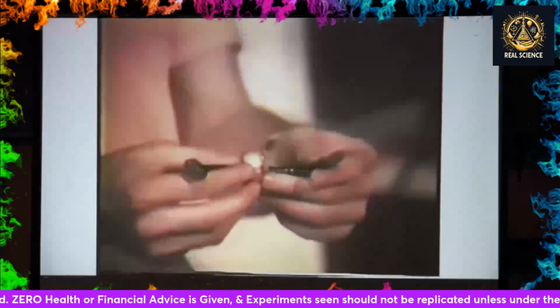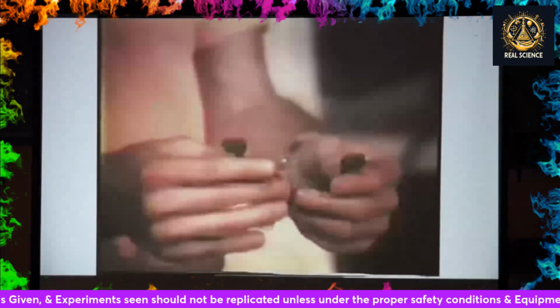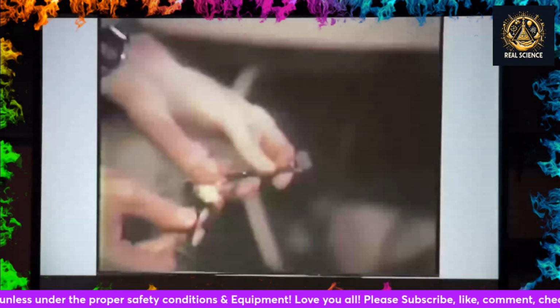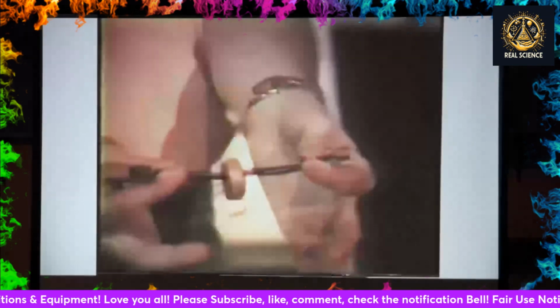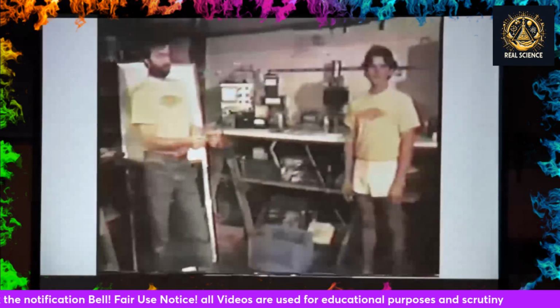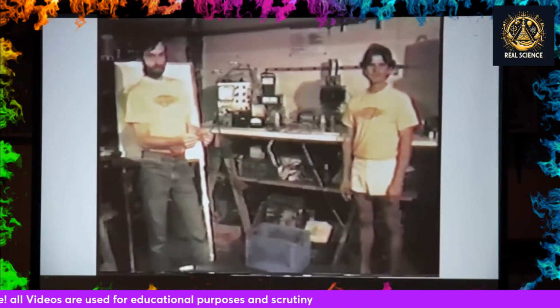You said that you witnessed heating of a conductor. Was it that conductor that heated up? This was the one, the very one, holding it in your hand. What gauge is that conductor? About 8 stranded? Show it to Chris. He would know the wire gauge right off. 10 gauge. 10 gauge stranded. Okay, and the length is about what? 5, 6 inches. And about roughly how hot would you say it got? You were holding it. It became uncomfortable after a while. Okay, that's about 110 degrees, 115 degrees.